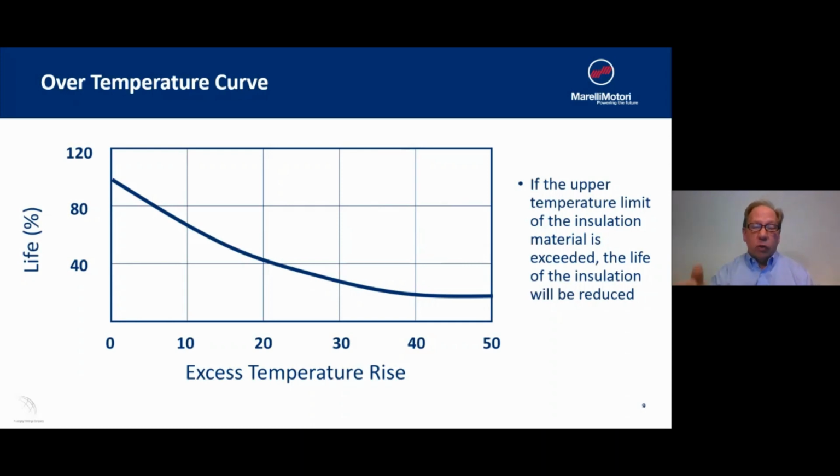Also, I mention this because a lot of times we work with customers who are replacing failed units. And it's important to understand why the unit you're replacing failed. If it failed due to a thermal condition, then you're best off to maybe upsize the next generator to give yourself a little more operating margin.